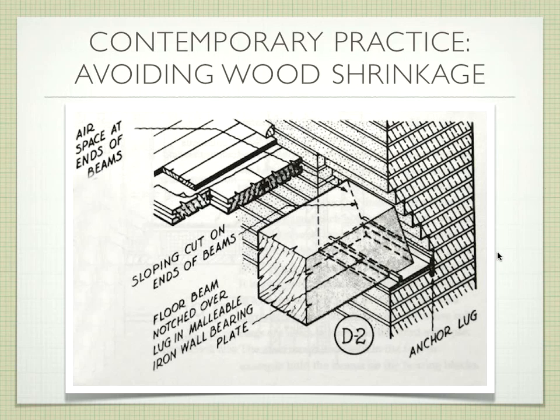This is where you have that malleable iron piece that I was talking about. So there's no bolts involved in this. The beam sets in and rests over that little piece so it can't slip out, right? It's relying on the weight of the beam not to slide out. But obviously, there's no bolts of any kind, so it can freely rotate if it were to fail. So it's just the older way of doing it.